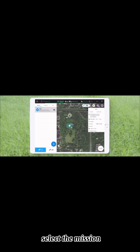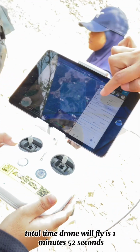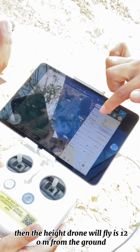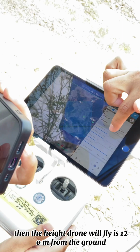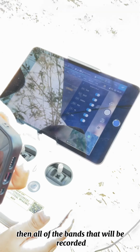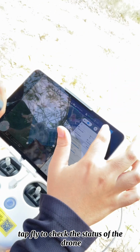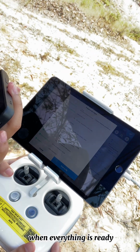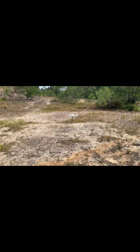Select the mission and check the parameter settings. Then tap edit. The total time the drone will fly is 1 minute 52 seconds. The height the drone will fly at is 122 meters from the ground. Then all of the bands that will be recorded. Tap Fly to check the status of the drone. When everything is ready, tap Start to Fly to begin the mission.